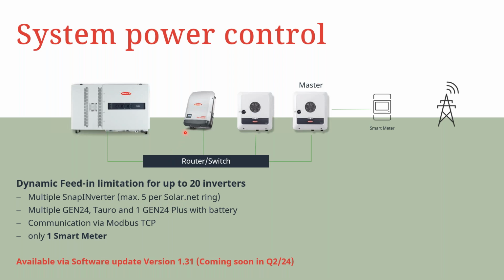By this, we mean that, for all those who are conversant with this, Snap inverters come in light and full versions. Light versions are data manager-less inverters, while the full versions are the inverters with data managers. And to implement the Solar Net ring, just like the name implies, it's a ring topology. So the inverters are connected communication-wise via a ring topology.